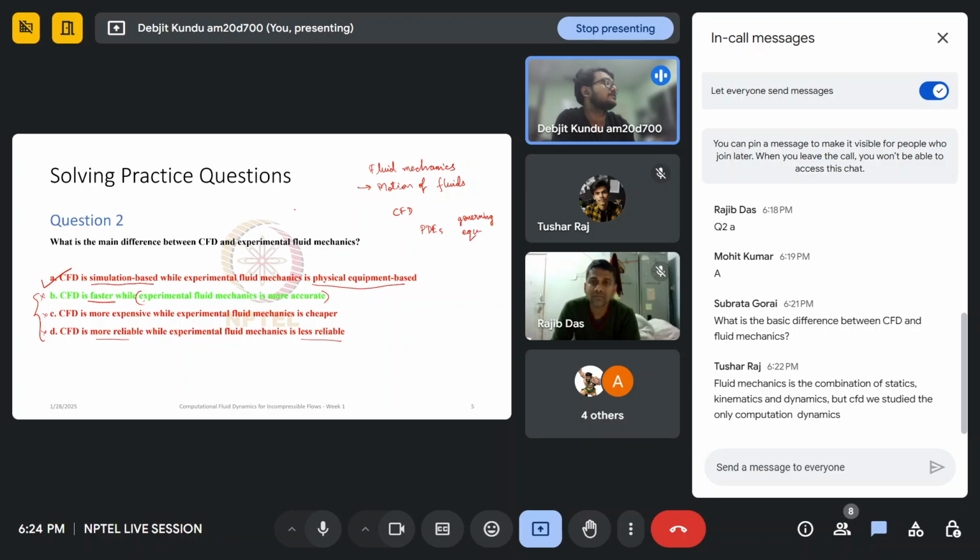So any fluid that flows will follow these governing equations. Now, these governing equations are not always solvable by hand. In some cases, they definitely are. If you have taken a course in fluid mechanics, you will learn how to solve basic cases like a Couette flow, where you have two plates, one of those plates moving, and you have some fluid in between, and you find out the velocity profile in between, right? I hope you're familiar with a case like this.